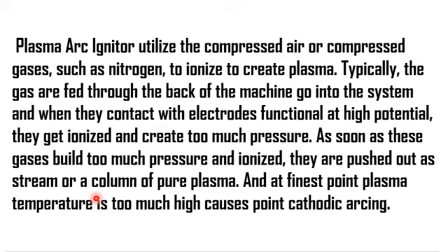When they pass through the orifice, the pressure and the temperature of the plasma reach their maximum, up to thousands of degrees centigrade, and in this way a stream of plasma is taken out from the instrument, which is then used in cathodic arc deposition as well as plasma arc welding, etc.